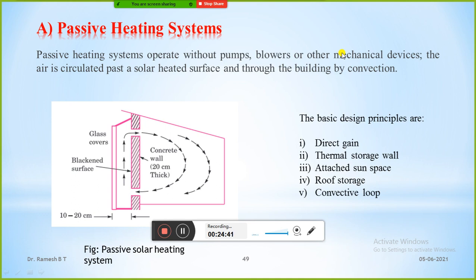It is more preferable in the northern hemisphere to face south, or in the southern hemisphere to face north, with arrangements to admit solar radiation, because these arrangements permit more solar radiation to be admitted. When the system is used for this, and sunshine is low in the winter, as we know, they have been termed solar houses.